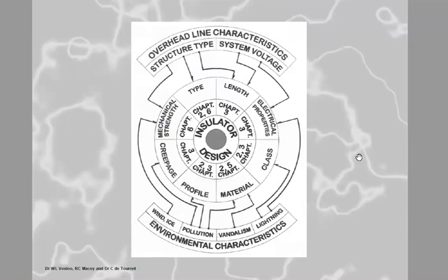The high voltage insulator needs to support the conductor mechanically, and it needs to insulate the high voltage from earth potential. If that insulator fails, the line is down, or the line is short-circuited to ground, and we have a flashover, and the line is taken out of service, which means loss to our customers. So the high voltage insulator is actually the backbone of our network.